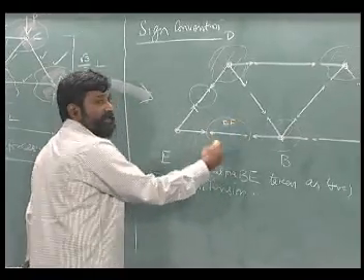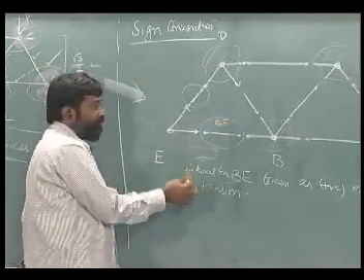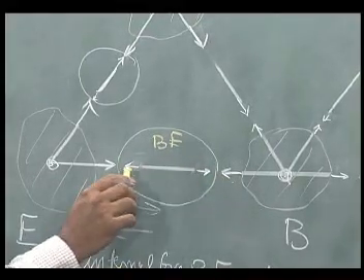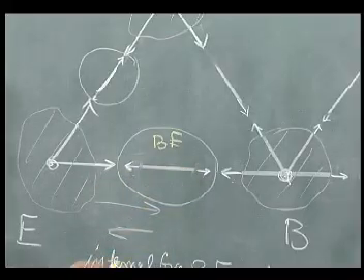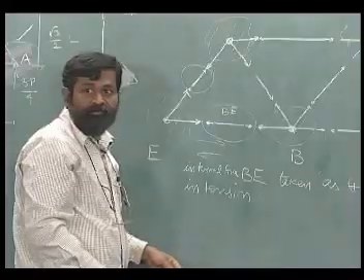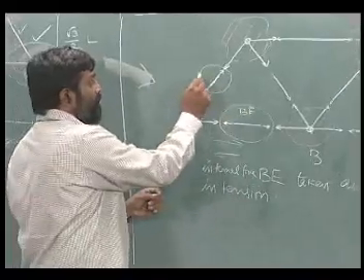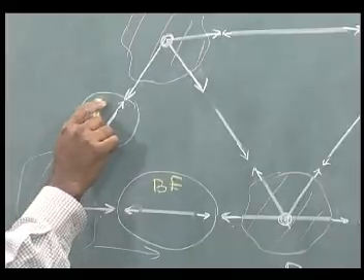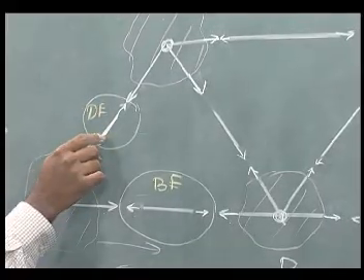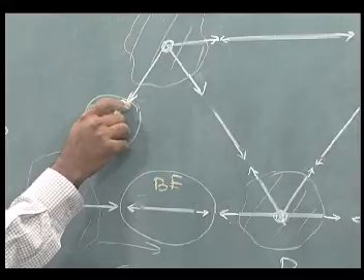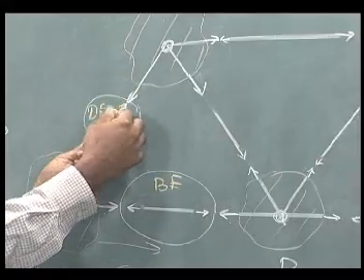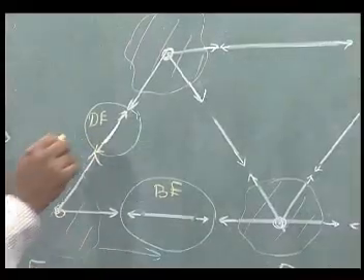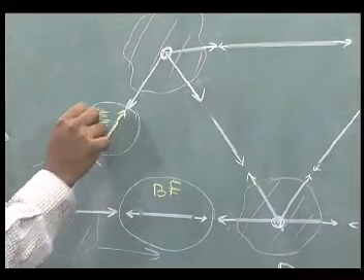I have just cut both sides, exposed the force. Remember, this is an equal and opposite, this is an equal and opposite. What kind of internal force is acting here? It is a tension force. How about here? This is member DE. Again I have indicated forces in such a way that this particular member is being pulled both sides. So this is also under tension.